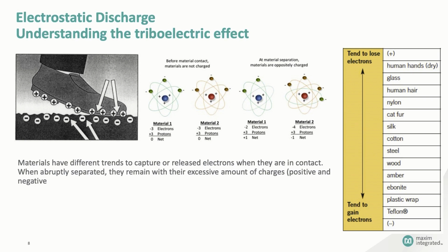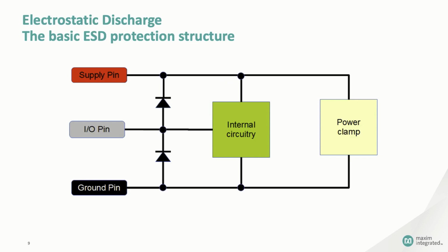First, all modern semiconductor devices, with some rare exceptions, include structures that mitigate the risk of electrostatic discharge. Now, notice that I said mitigate and not eliminate. You can still overwhelm the protection circuitry with enough electrostatic energy, but these protection mechanisms are a vast improvement over exposing an unprotected MOS gate to the outside world.